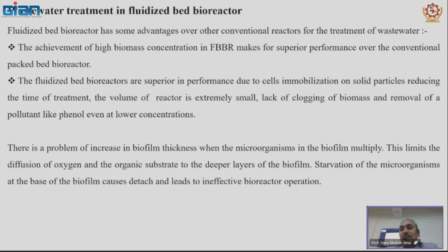So to the deeper layer, oxygen does not reach, or other nutrients do not reach, even the substrate, which is nothing but the kind of food to the microorganism, does not reach, so those microorganisms die. As they die, they lose contact from the solid surface, so washout of the biomass occurs. That is the disadvantage here.